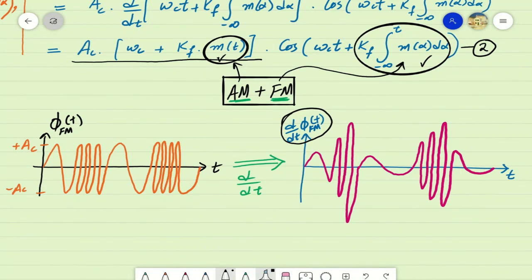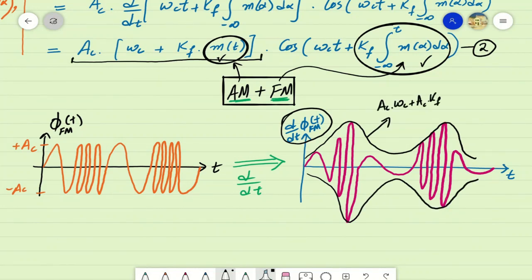For the time spans where we have a low amplitude, we also have a low frequency, that is the number of cycles per second experienced by this signal. And for the time spans where we have high frequency, we also have a high peak amplitude of the modulated signal, as the frequency and amplitude are directly being modified with respect to the amplitude of the information signal. That is, the envelope of this signal represents the information signal in its original form, which is equal to the information signal if we ignore the scaling and shifting parameters that are constant numbers here.